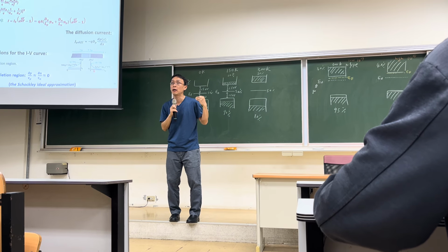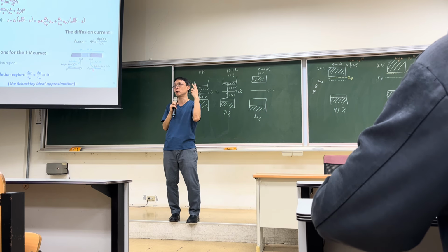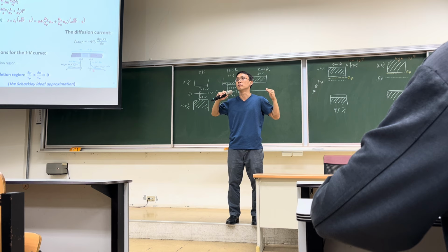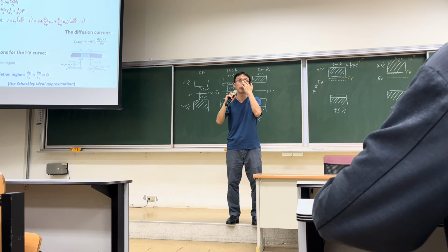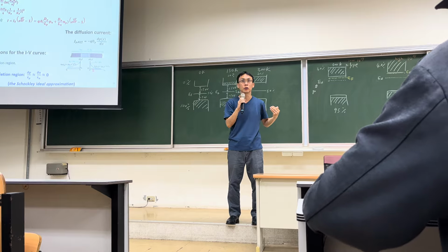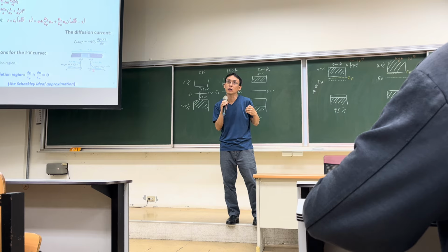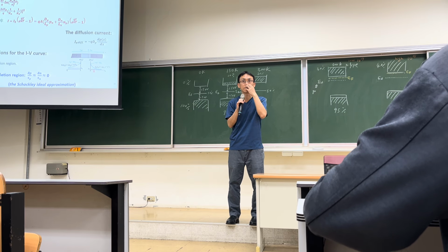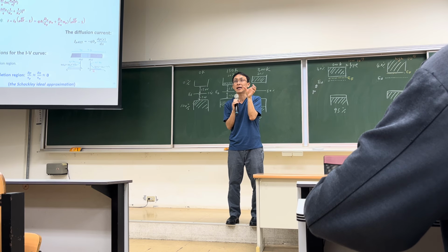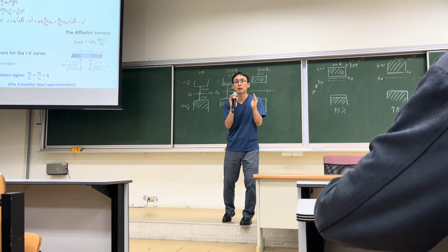You need the equation to evaluate the turn-on voltage or the contact potential. That's the first equation. Second equation, you need to know the width of the depletion region. That is especially important for optical devices like a solar cell or photodetector, because the useful currents excited by the photons of sunlight come from the depletion region. You only have the electrical field inside the depletion region, right? So you need to know the width of the depletion region.